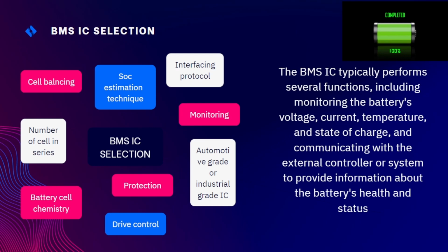Next one is the interface protocol. If you are using an external IC for some of the capability, you will need to connect it to the BMS IC and use some communication protocol so that the two ICs can communicate with each other. Therefore, your BMS IC must have an interfacing protocol, whether it be UART, I2C, SPI, etc., to be able to communicate with the external IC. If you are just using the BMS IC standalone, then you won't have to worry about an interfacing protocol, as you don't require external communication with another IC.